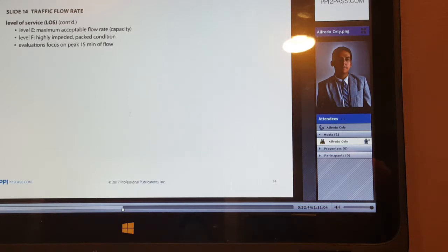Now, for roadways that have a lower level of service, it typically indicates that the roadway is functioning at a packed condition and can be interpreted as less safe. The notion that the roadway is less safe when you have a lower level of service is all related to density. There are more cars on the highway, and first of all, they're all driving a little bit slower, right?